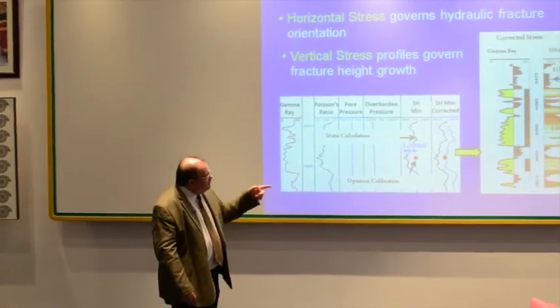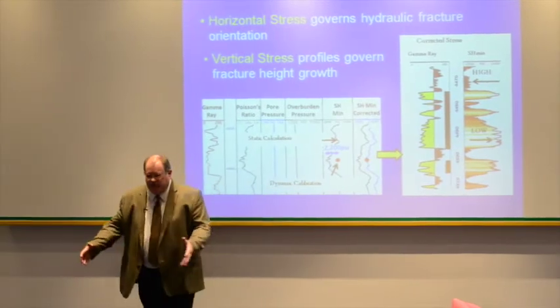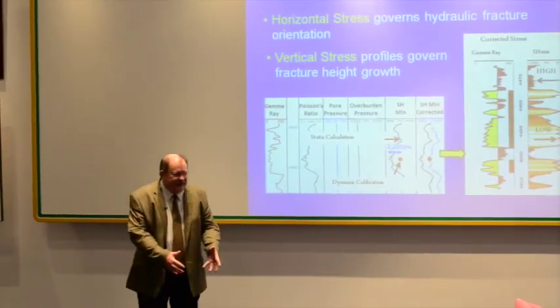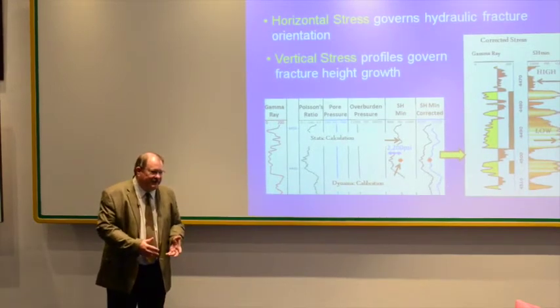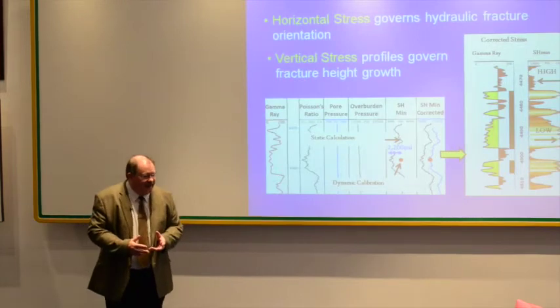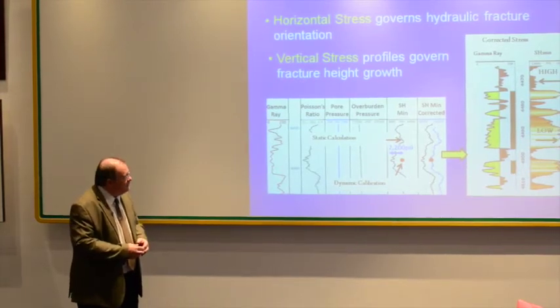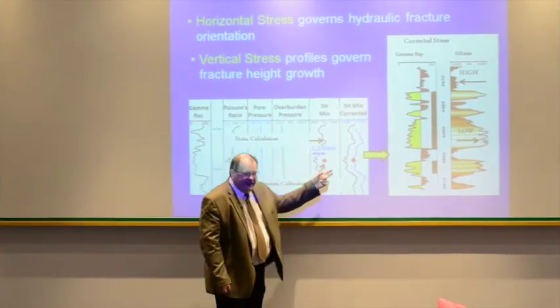So once you do that, there's all kinds of things that happen on this tail end. Some people will do a bulk tectonic correction. Other people will expand that to utilize Young's modulus and wellbore stability theory geometry to try to get a better handle on the maximum horizontal stress. But at the end of the day, it's nothing like field data to calibrate those.